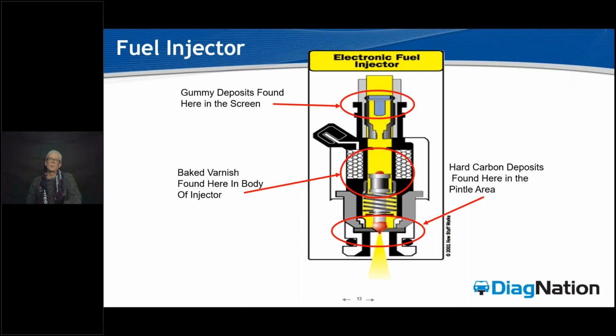Okay, because this is where we're getting a tremendous amount of problematic wear in the GDI injectors. And there's so much finer tolerance and so much higher current injectors. Some of them fire up as high as 80 or 90 volts, that it just can't hang like the old days with the low pressure injectors.